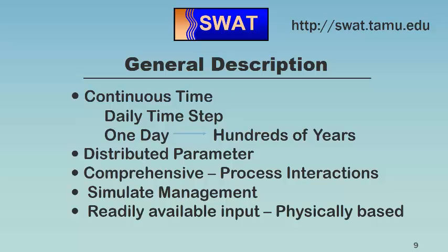In general, SWAT is a continuous time step model. You can run the model from a few days, weeks, months to all the way to hundreds of years. And it's a daily time step model. That's what it's predominantly used for, but the model is capable of simulating at a sub-daily time step also, provided you have the proper weather data to support a sub-daily time step, for hydrology and sediment only at this point.